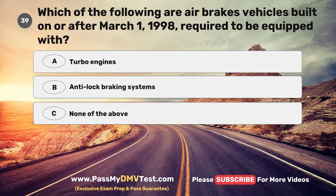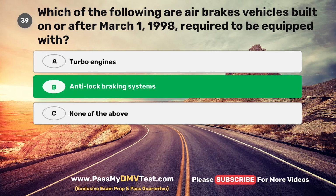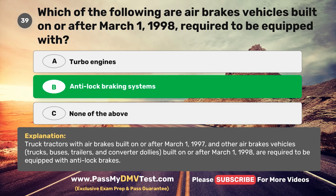Question 39. Which of the following are air brake vehicles built on or after March 1, 1998, required to be equipped with? A. Turbo engines. B. Anti-lock braking systems. C. None of the above. The correct answer is B. Anti-lock braking systems. Truck tractors with air brakes built on or after March 1, 1997, and other air brake vehicles, trucks, buses, trailers, and converter dollies, built on or after March 1, 1998, are required to be equipped with anti-lock brakes.